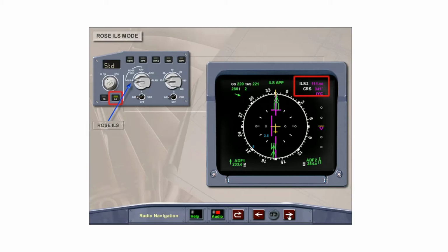The crossover of ILS information on the nav displays is evident with ILS 2 being displayed on Nav Display 1. The ILS course, selected either automatically or manually through the MCDU, is displayed by a magenta dagger-shaped pointer. The lateral deviation bar displays the localizer deviation.